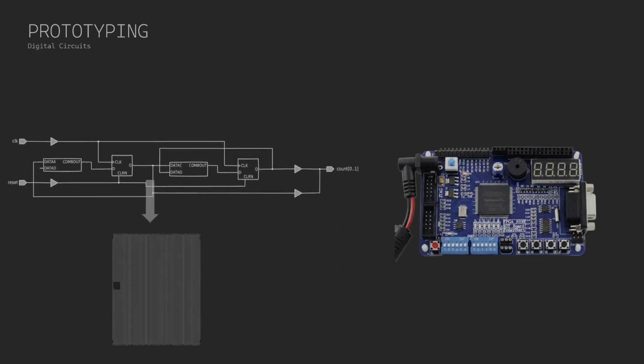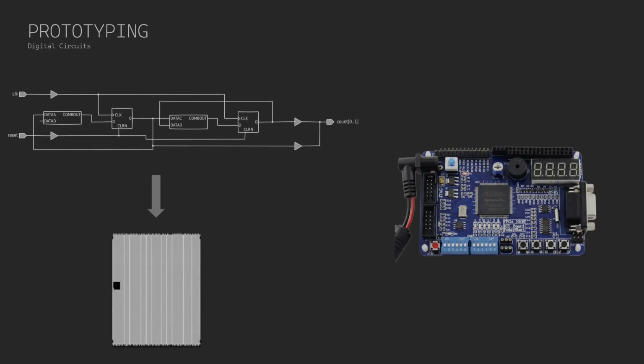In implementation, also known as place and route, PNR, the tool virtually maps the synthesized logic onto locations in the FPGA's internal fabric, and then makes the connections between the components, also known as routing. The connections will use the routing resources which are already present between these components. Program file generation: after successful implementation, the tool creates a programming file for the FPGA that we dump onto the FPGA. Once programmed, the circuit is realized instantly within the chip.